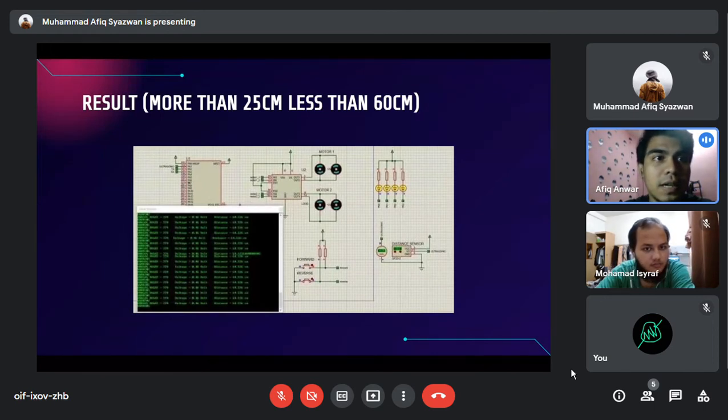If the distance is 25 to 60 cm, it will show the warning that you are closing. The message is sent to the driver and 4 LEDs will blink with 50 millisecond delay. Meanwhile, if the distance is less than 25 cm,